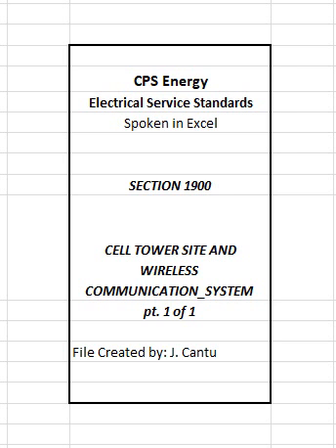Where multiple single-phase meter sockets are installed on a 3-phase service, the single-phase loads shall be balanced between the 3 phases. Note: it is the responsibility of the customer requesting the upgrade or redesign of an existing service to schedule the necessary power interruption(s) with other cell site customers while maintaining communication and coordination with CPS Energy.